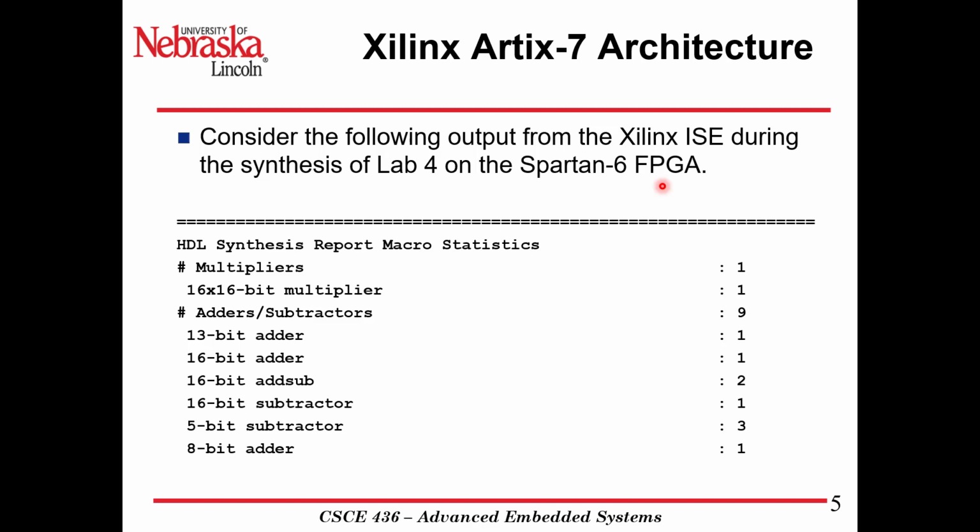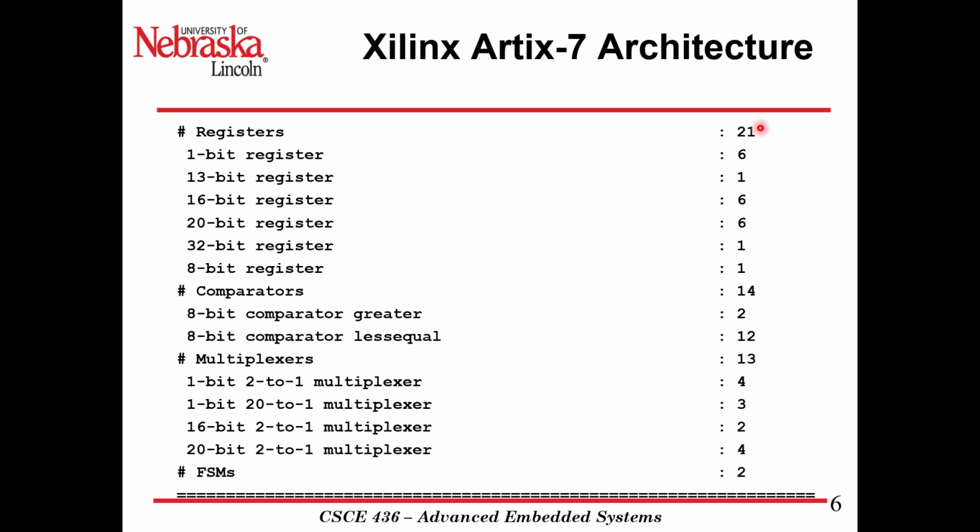The report looked a little different in ISE versus Vivado, but it shows you all the primitives, the basic medium-scale logic blocks that are being used by that design, where we're using 13-bit adders, 16-bit adders, 8-bit adders, subtractors, things like that, and a 16 by 16 multiplier. And we know what that's for Lab 4. That's to calculate our amplitude. So we're multiplying those 16-bit values and then taking the top 16 bits for our output.